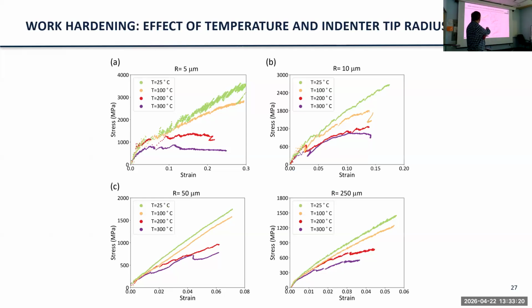Okay. So the last thing from the bulk curves is this is looking at how the indentation stress strain curves vary. Let's maybe focus on this 250. So again, the elastic portions down here, and then you can see that the hardening during the indentation test varies with temperature, right? So this is 300, 200, 125 degrees Celsius. So we have some measure of the relaxation of the stresses in the material during plastic deformation.